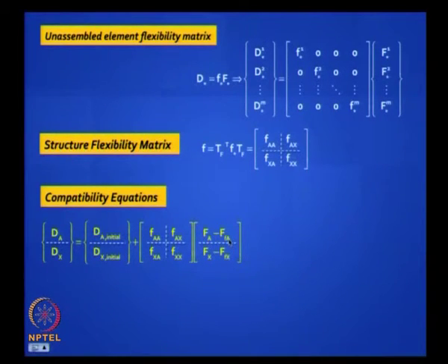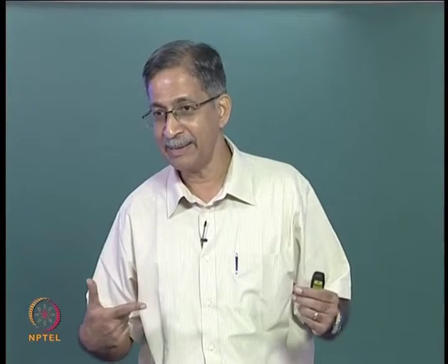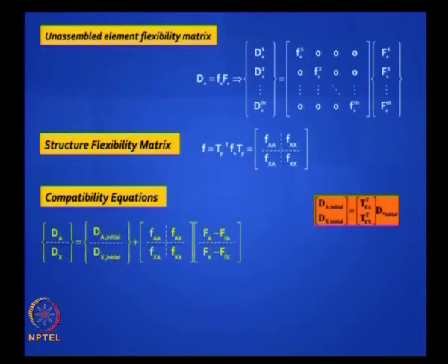Now sometimes you have some fixed end forces, not in trusses, but remember the axial element problem, you had some loads acting in the middle, we will do one problem of that kind, then you will have some fixed end forces which you have to bring in. So in such problems FFA and FFX will come, that is, you can get your initial joint displacements through this transformation both at the active coordinates and at the redundant coordinates, and you get your net load vector FA minus FFA.